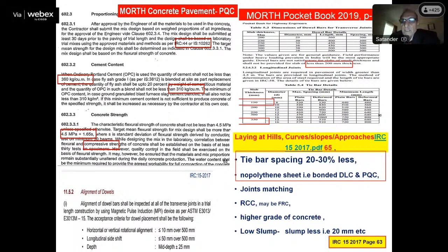Load is not there. The dowel bar's technical name is load transfer device. So in PMGSY, because load is not there, we are not using dowel bar at each contraction joint. But in national highway, everywhere we are using. And another thing, every contractor wants, they don't want 36, 38 mm at site wherever it is required. Like for 300, we need 38.